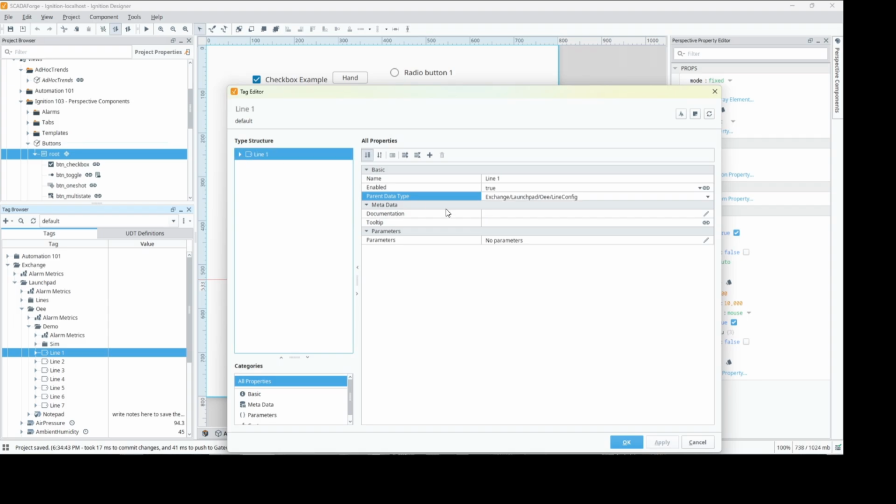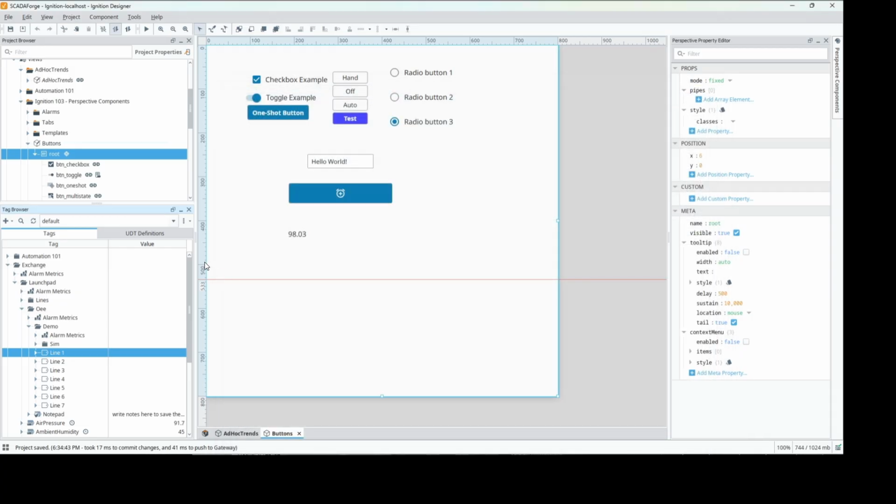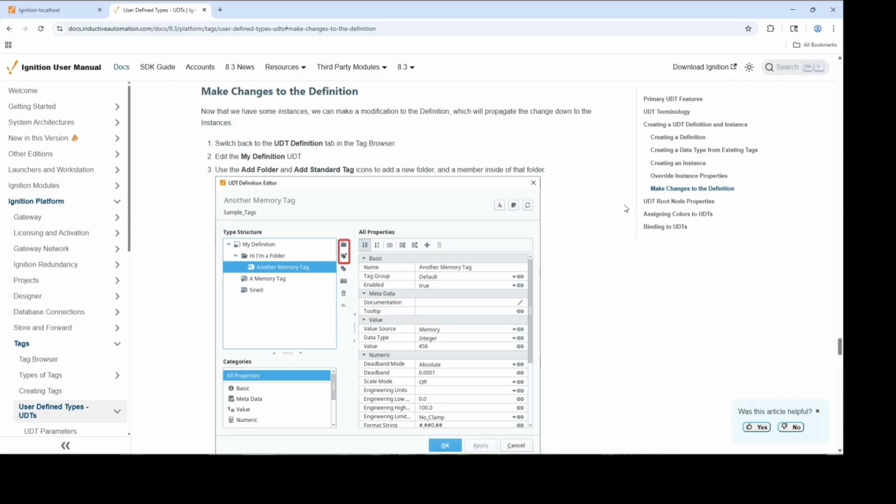These will really come into play when we're doing templates. Let's say we have 50 valves in the field at a factory, and we want to pull the same data across for all those; we would build a valve UDT for that. But this is more just high level. The UDTs exist, and those are a very powerful tool in the Ignition ecosystem.